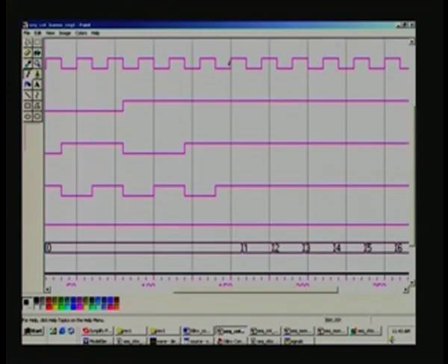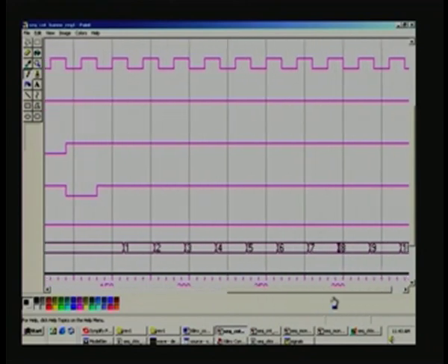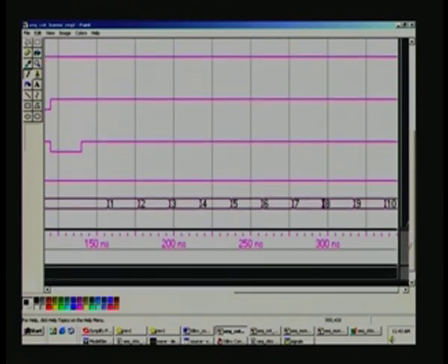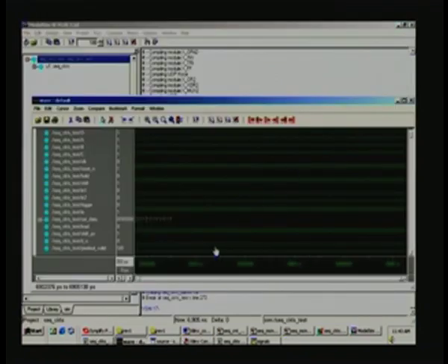Now you can have a look at the difference. See here the positive edge of the clock occurs here, whereas the actual count takes place only here. This is clearly due to the gate delays associated with the circuitry for that particular path, and so is the case. You can see equal amounts it is shifted from every clock here, and clock frequency is I think the same, 50 megahertz, 20 nanosecond I think. So, we will open another, this is going right up to 10. So, we will continue, towards the end we will see.